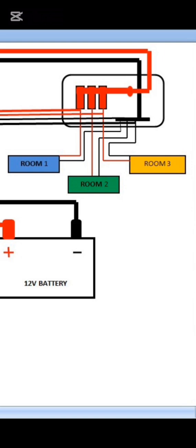Since you are connecting the AC output of the inverter to room 2 and room 3, you must switch off the circuit breakers of room 2 and room 3 to disconnect the positive power supply from the main, that's from the meter or main power supply, so that only the power supply of the EPS will be supplying the power to room 2 and room 3.